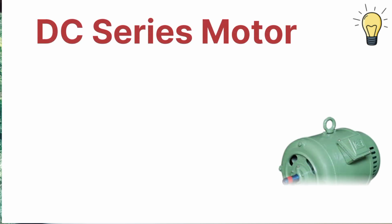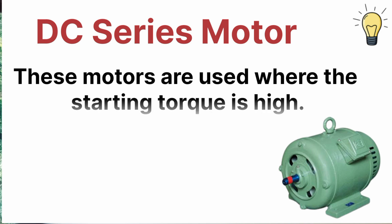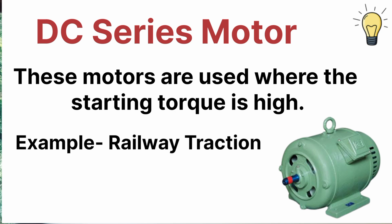Okay, so now let's talk about the DC series motor. DC series motors are the motors which are used in applications where the starting torque is more important. That means, for example, in railway traction the starting torque is more important, so in that case we are using the DC series motor.